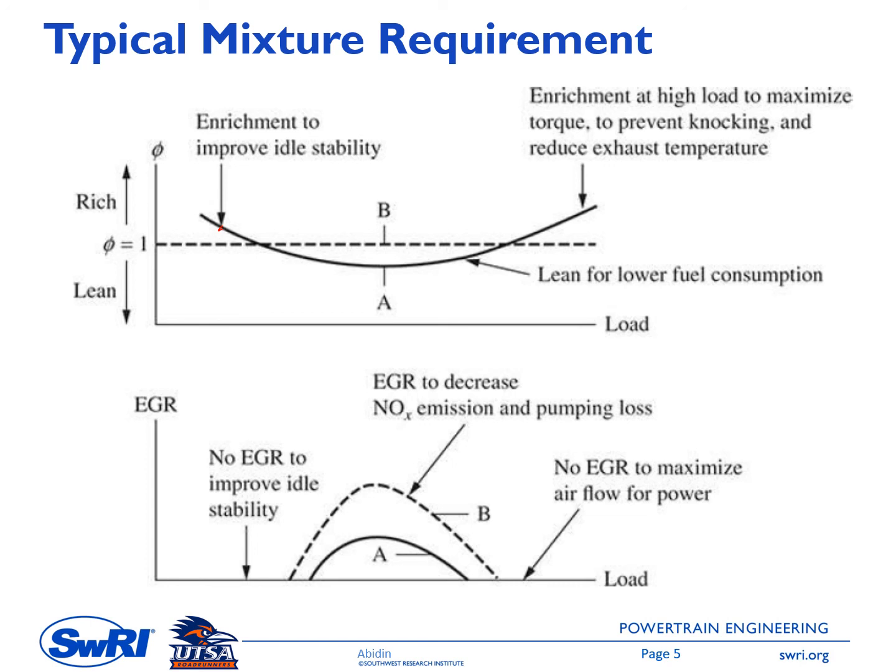When you look at strategy B, the phi is held constant at stoichiometric condition. By having a stoichiometric mixture with phi of 1, we can use a three-way catalyst. The three-way catalyst is one of the aftertreatment systems that can remove CO, NOx, and unburned hydrocarbons simultaneously. So it removes three emission components: CO, unburned hydrocarbon, and NOx. But there is a strong requirement for the effectiveness of the three-way catalyst, which is stoichiometric mixture combustion. Therefore, strategy B, which is designed to optimize for emission reduction, is operated under stoichiometric condition over all engine load levels. So you can see there that B has a horizontal line, and this axis is the load, and this one is the phi.